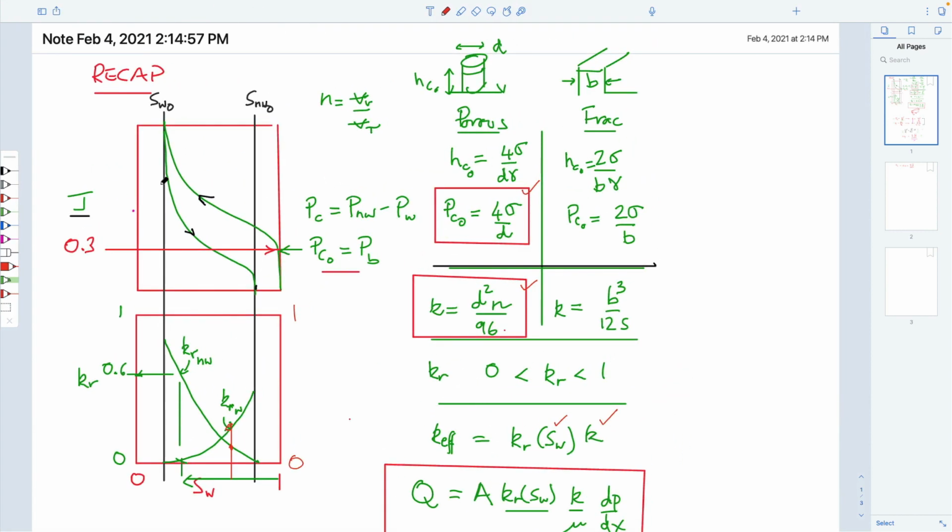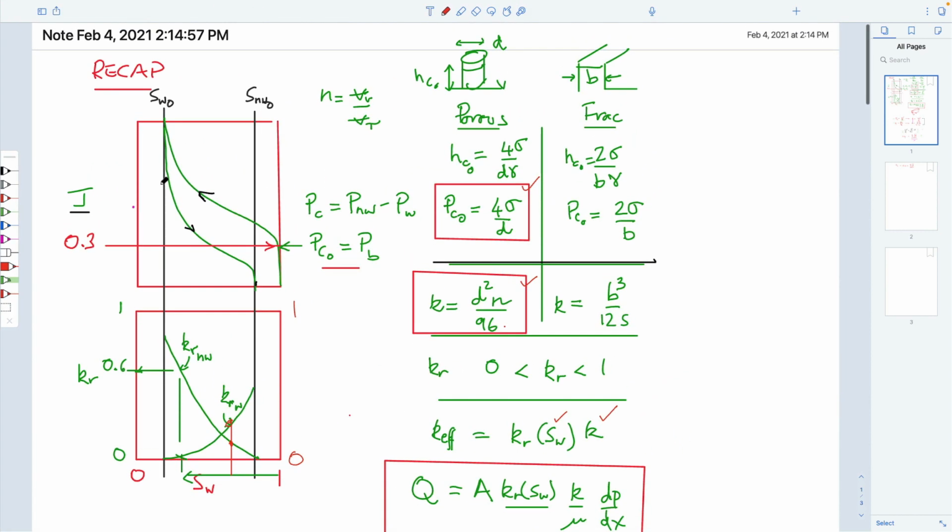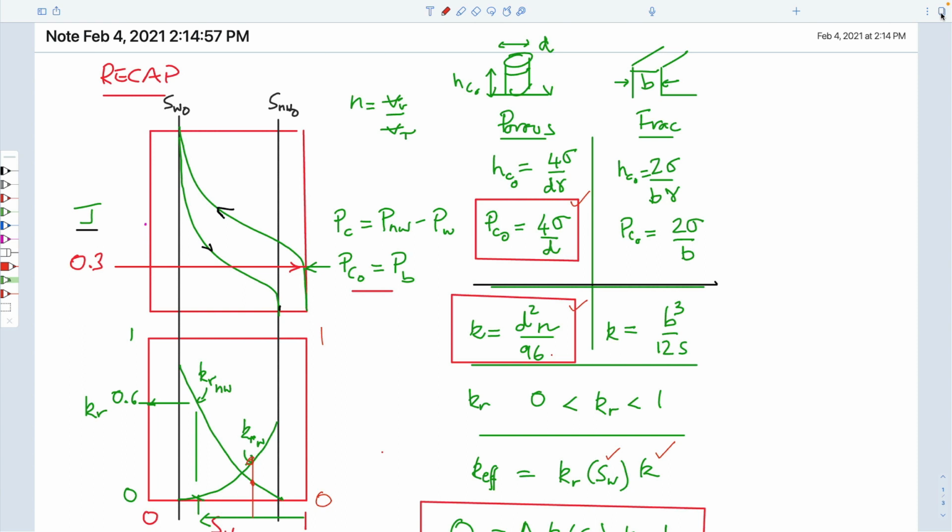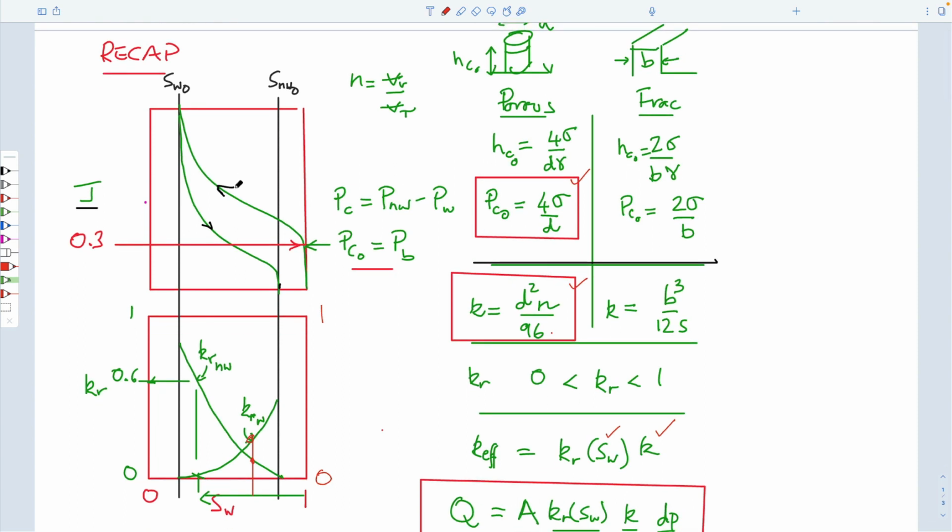So, the second recap then, I suppose it's easy just to come back to this. This actually embodies everything we've talked about so far. And that is that the distribution of fluids as they go in the subsurface in the first couple of months is controlled by this diagram on the top, the capillary pressure versus saturation diagram. We know it's hysteretic. We know some of the ordinates on this are the bubbling pressures, where a non-wetting fluid breaks in as a bubble into the system and then displaces water back towards reduced saturation.